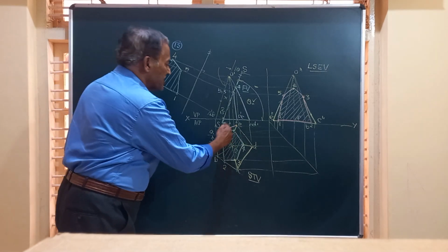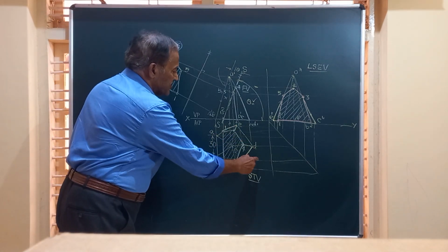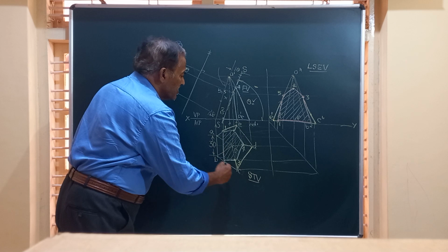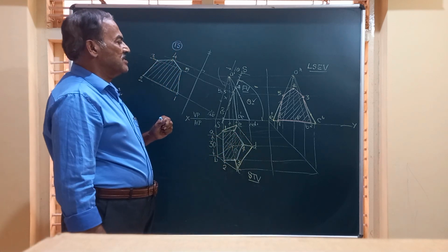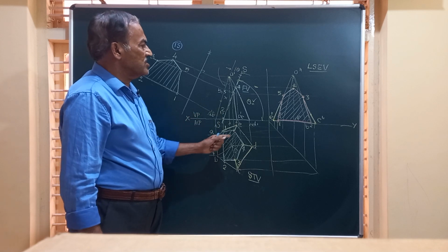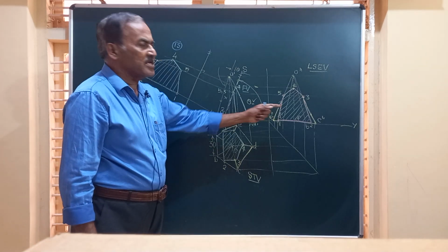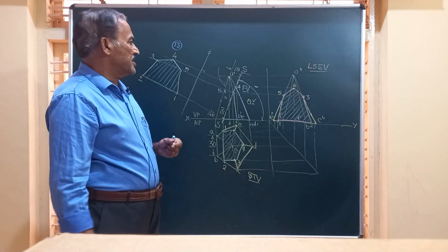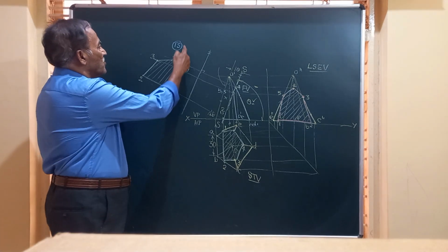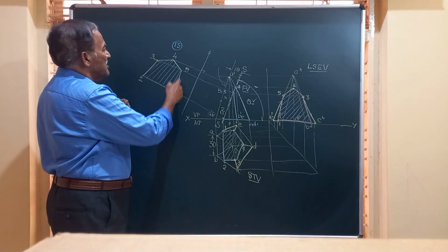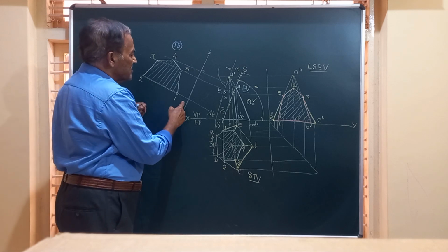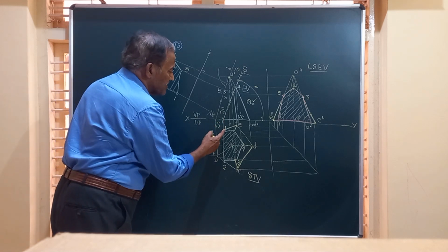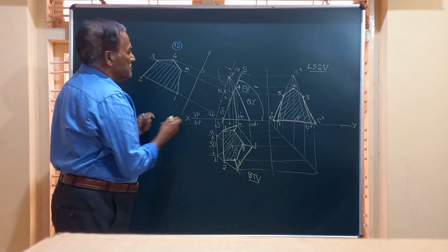Next, we have the top view with the section part, and this will give you the sectional top view of the solid. So, based on this, we have got the sectional end view or left sectional end view. Finally, we have got the true shape of section, a distorted pentagon, and we have taken all these distances from the XY to the corresponding points.